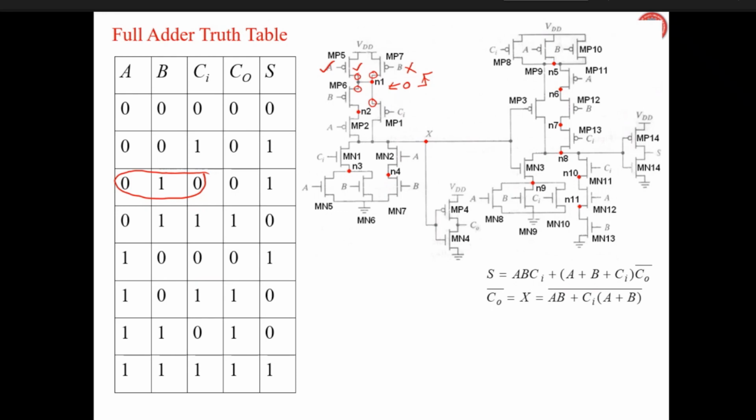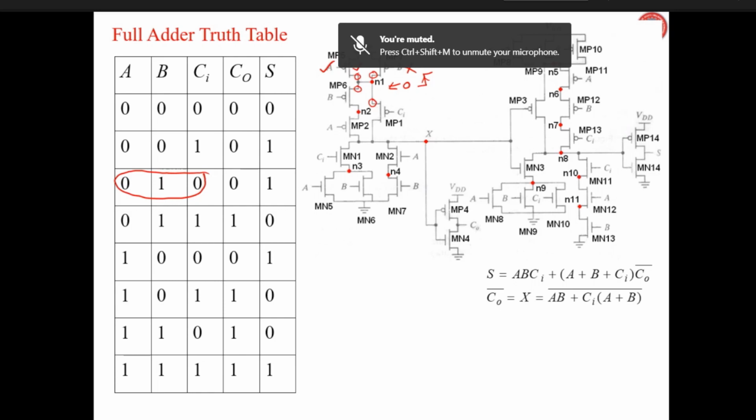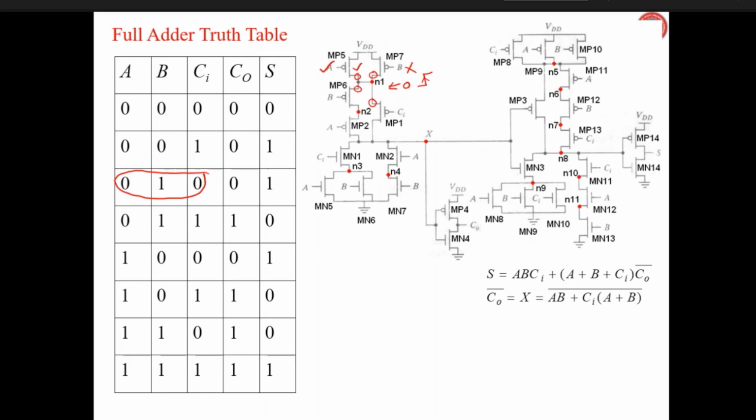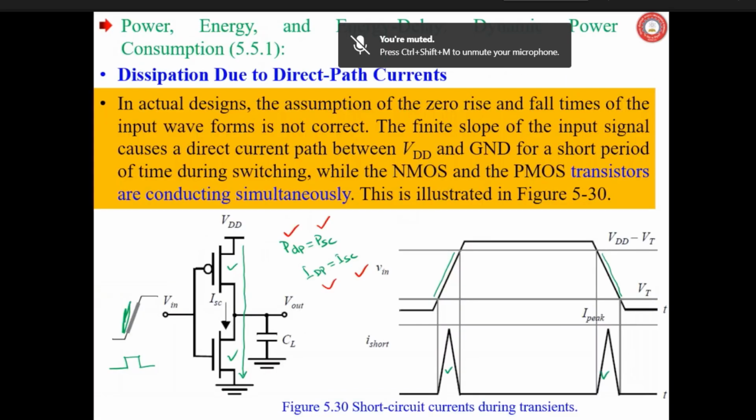But it doesn't mean that always in the chip there will be only a two-input NAND gate. Maybe three-input or four-input also. Normally it doesn't exceed this number, because again the pull-down network will be connected in series, and then TPHL will be much longer. Understood? Okay. Now we are here.